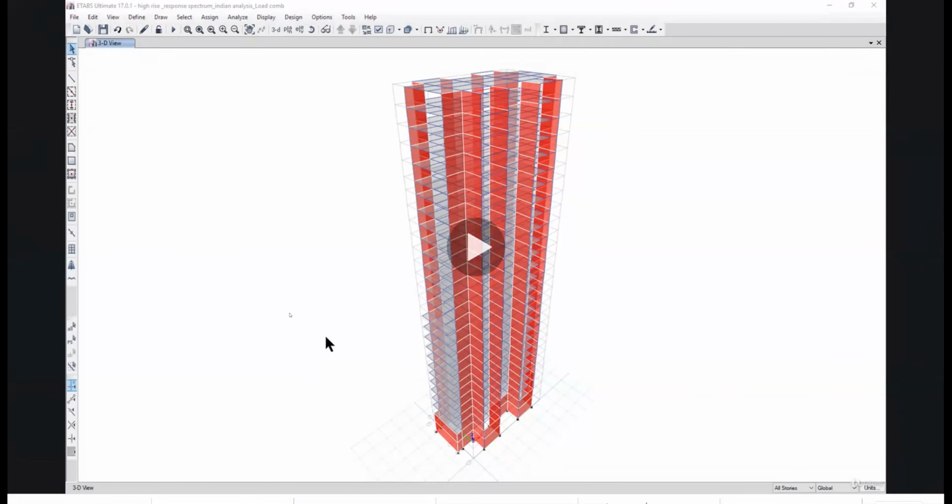Whatever building you have modeled so far, and whatever approach you have come up with, different types of loadings, dead loads, live loads, and earthquake and wind loads, apply all the loads and go with the design. It is only a few steps in designing. It is not at all difficult. It is like having a number of buttons available, like a switchboard or some kind of video game. You can just go there, select the code book, then select the load combinations, and then go for analysis and design check. Those are the only steps anywhere.